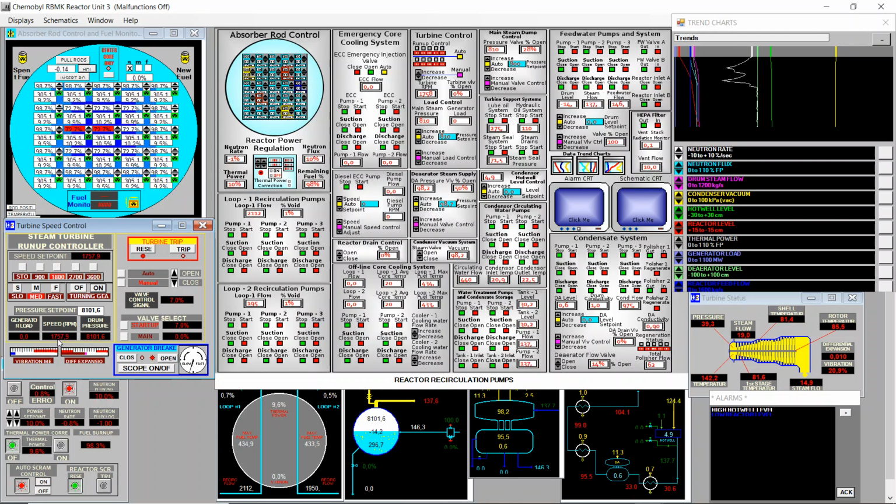Even if it now increases speed very fast, you will see that the speed will slow down if you keep the valve open at the same amount all the time, because the friction and the losses because of turbulence in the fluid increase with the speed of the turbine. So I will increase the valve opening to 12, let's say, and now we see it increasing very nicely.